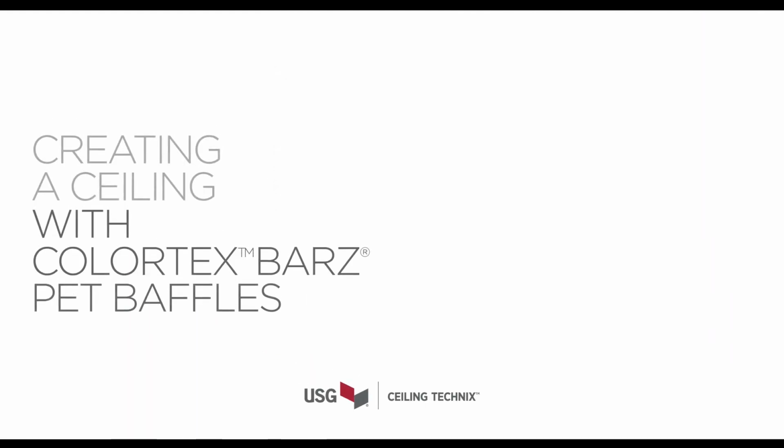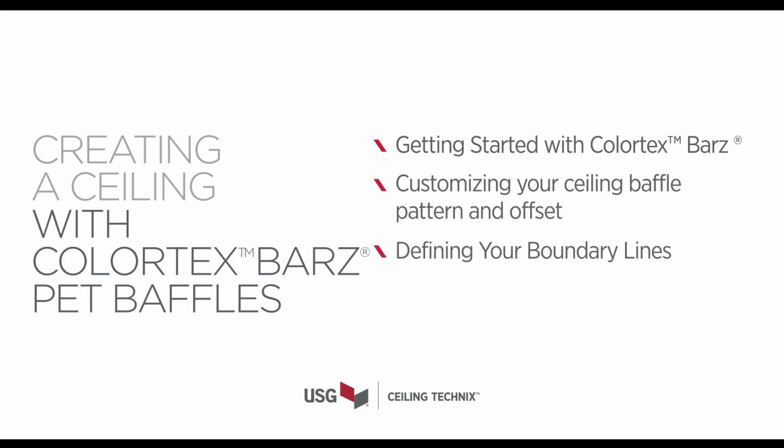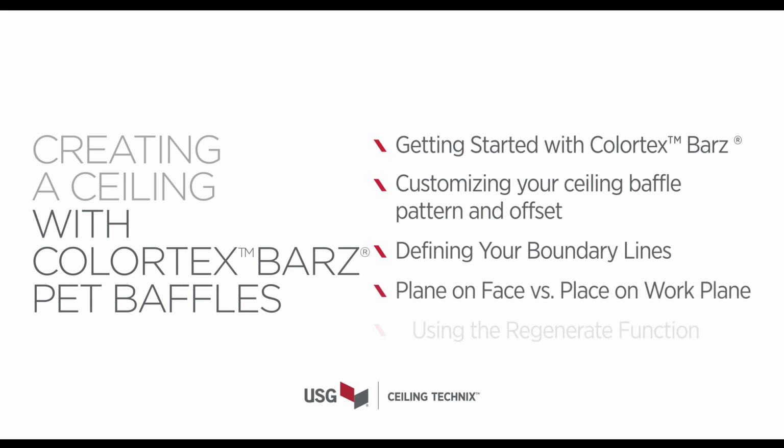Creating a ceiling with design solution Colortex Barz PET baffles. In this video, we'll explore how to get started with Colortex Barz PET baffles, creating and customizing your ceiling using a preset pattern and starting from scratch, drawing boundary lines, when to use place on face and when to use place on work plane, and how to use the regenerate function to iterate on a ceiling within the same session.